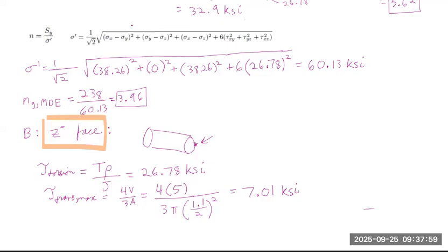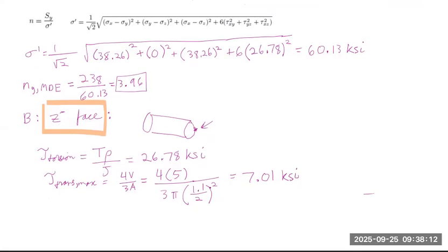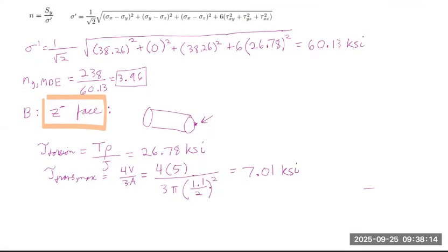So as we mentioned earlier, the normal stress due to bending at this face is 0 since this face lies on the neutral axis of the shaft. We now have two shear stress components, so we have to figure out a way to add those up. Let's first figure out whether they point in the same direction. We already have the diagram over here, so I'll use this. The torsion vectors are going like this, so the shear stress due to torsion is pointing up.